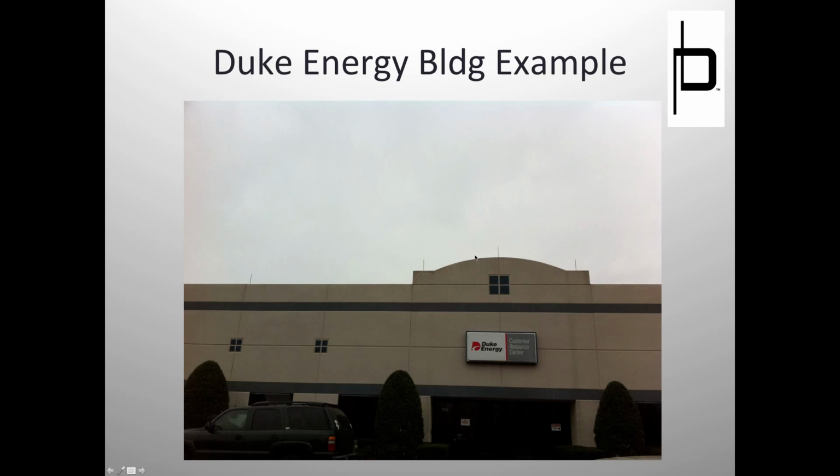But these on the right have to be closer together because you have a bit of an arch, right? Absolutely. That's a very good observation. The reason these are closer together is because the sphere, if you take this one away, the bottom of the sphere would cut into that top part of the building. And then that top part would be subject to lightning strikes. They want the lightning to go here because this is connected to some sort of grounding system or down conductor that is then grounded, and it's much safer for the strike to go there as opposed to creating a fire or who knows where it's going to go if it was to strike here. So that's why they added that extra one right there, because of that arch.